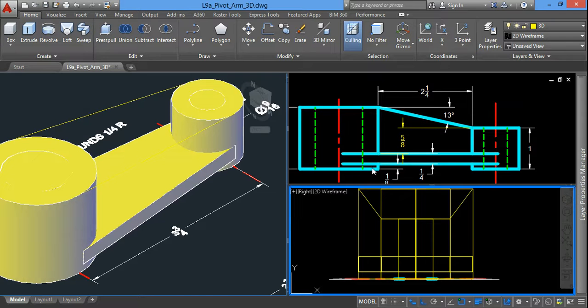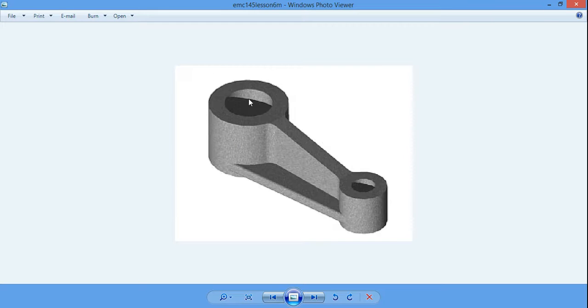Alright, so that feature is complete. So we're going to have a cylinder removed from the entire feature that needs to be subtracted out of the object. As you recall, we just made a base that is currently cutting through the cylinder. So we are going to subtract the cylinder from not only this large feature and this small cylinder, we're also going to subtract it out of this base. So watch the technique as I use a command called subtract to remove the holes from these features.